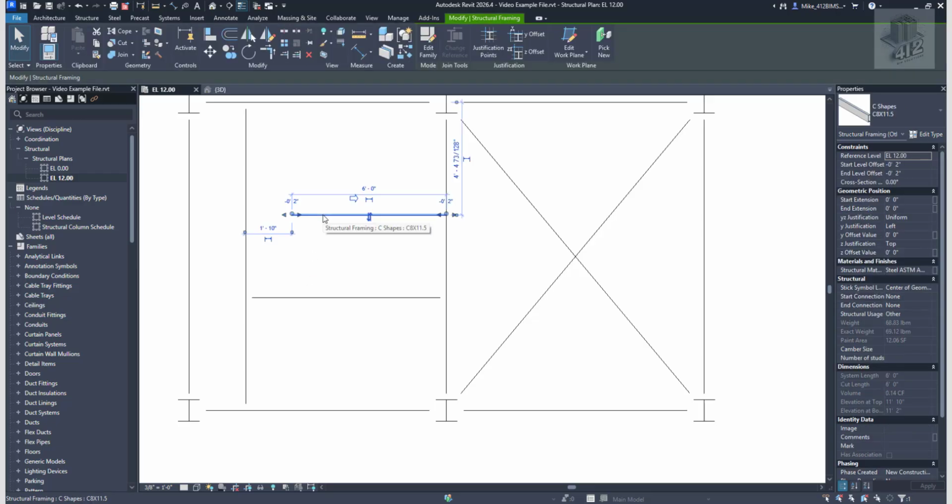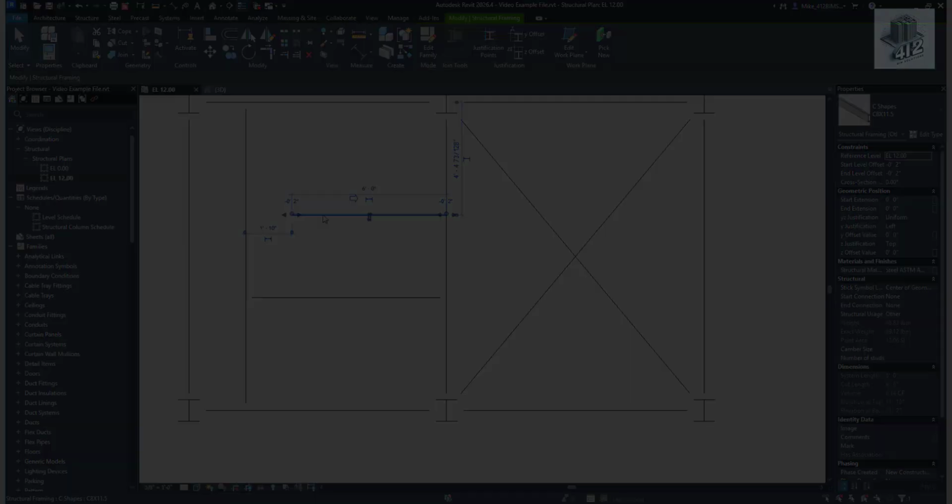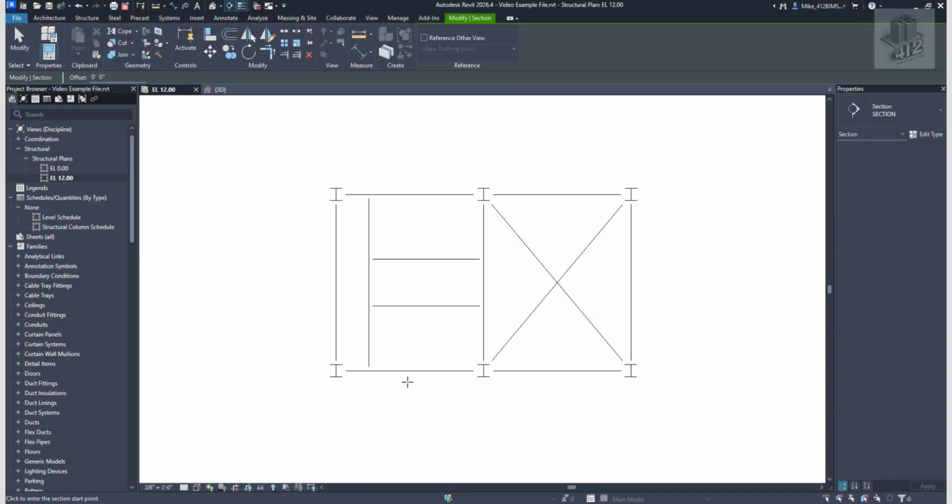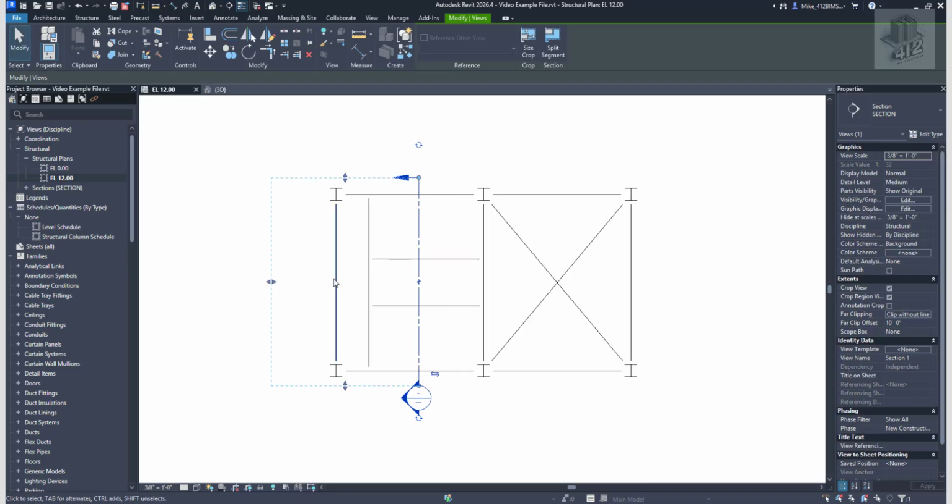This one here, you've just set the justification line to be 2 inches lower than the justification line of the beam that you're connecting to. Now they are misaligned vertically and will not respond to each other. So if I was to go and cut a section looking this way, I don't want to see all that. I just want to see these channels.